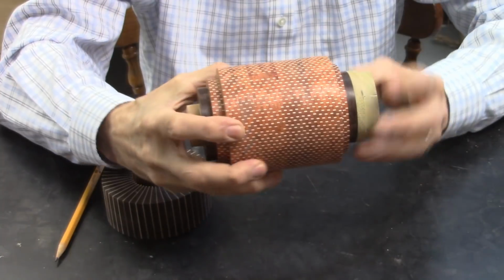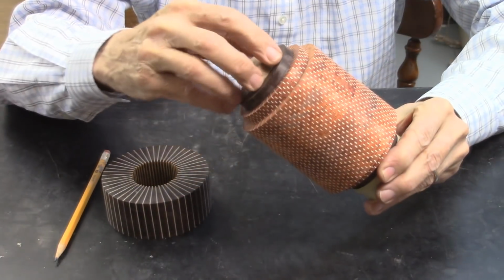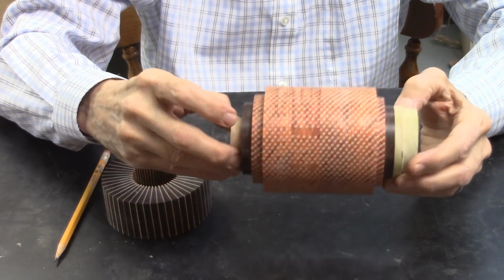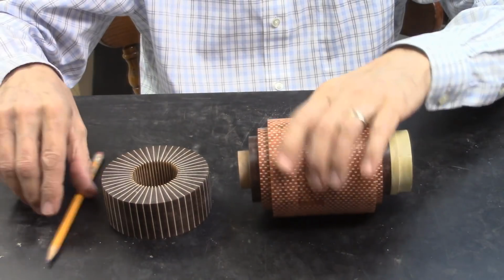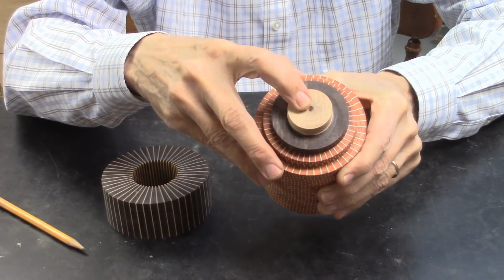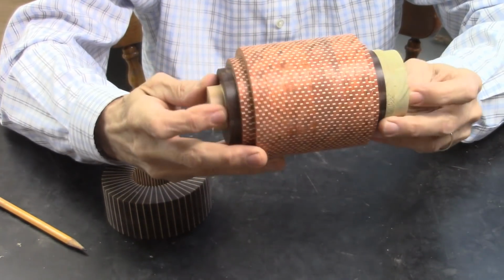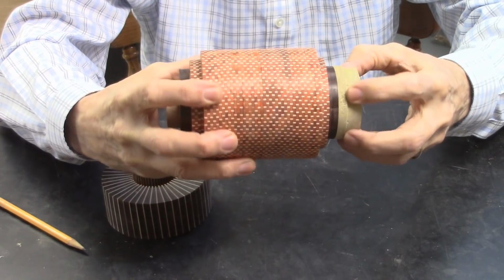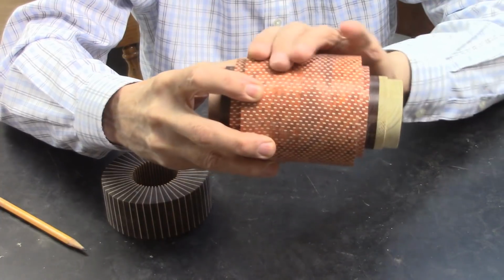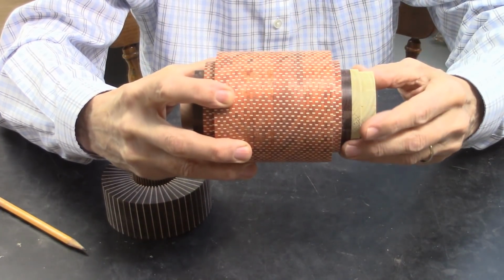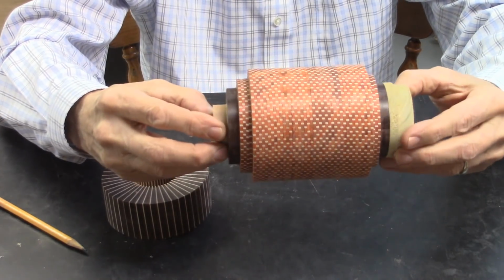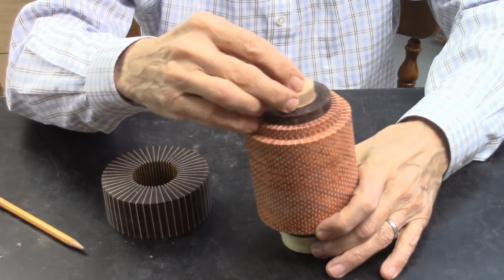I also then added a piece of round stock on the bottom and top, which will later be cut off on the lathe, and I just used these so that I can center it on the lathe. What I did is I put this on a table and I just rotated it to locate my centers on both ends, and then I put center points on this, put it in the lathe, turned it, and then turned this down so that it fits my chuck. It'll be centered based on the OD of this main body of the future egg. And so this is ready to go in the lathe now, and we'll turn this down to our finished egg.